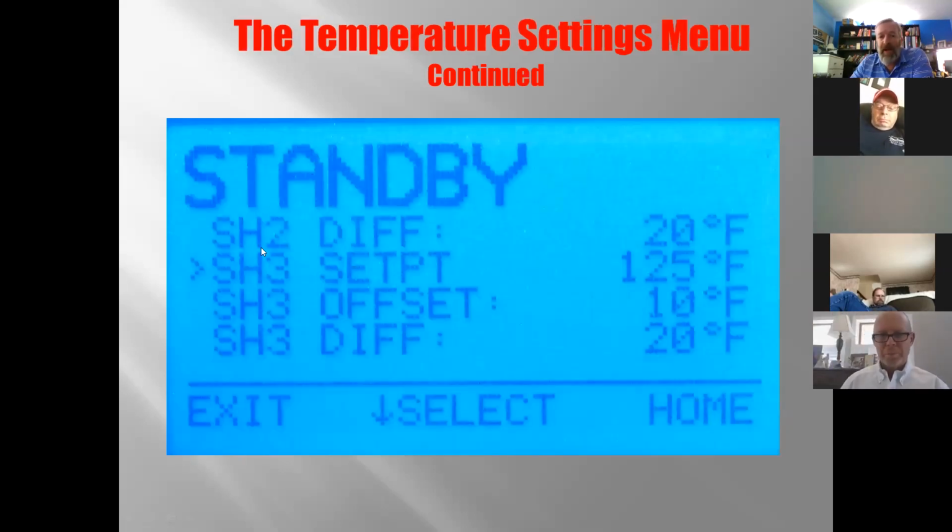Okay? But here's all our set points, everything else. We have 3 opportunities to do it. Why? Well, because we can, so why not do it? I can do baseboard, radiant, and hydro-air, and if I bring those 3 separate calls, the boiler's going to be able to differentiate what's calling and what it should do. So if you're using radiant a lot, that's your main thing, and every once in a while you have to pick up with hydro-air, you don't need the boiler to run at the hydro-air temperature all the time. It can run at the radiant temperature. When it needs to, it can bump up and go. Okay?